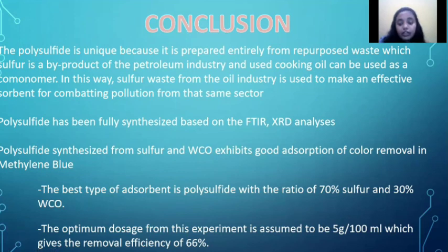So polysulfide can be the best adsorbent to treat colored wastewater, because polysulfide has both hydrophobic and hydrophilic characteristics, which can go well with the water properties of the wastewater.